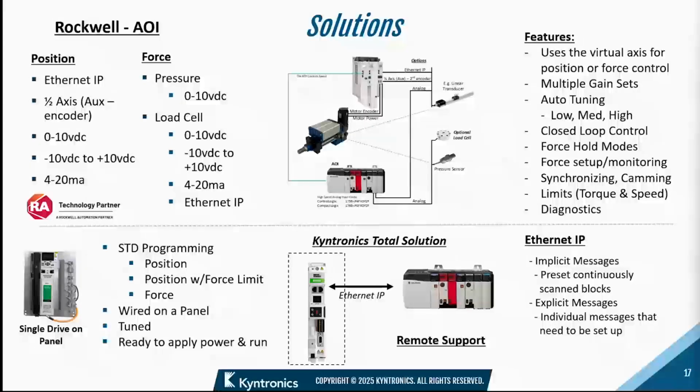So for those of you out there that use the Rockwell system, we have an AOI with that same software. So the AOI is, all that software was plugged into the AOI. So you have all those capabilities along with some other capabilities, including auto tuning, you have multiple gain sets. You can do synchronizing and all sorts of things with the AOI itself. We have some example code. And below the dotted line, you have the Kyntronics solution that can talk Ethernet IP that will do the implicit messages or explicit messages as needed. Again, both are easily supported from our experts here at the factory.